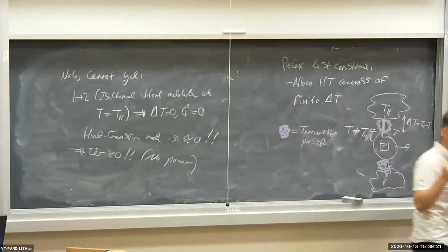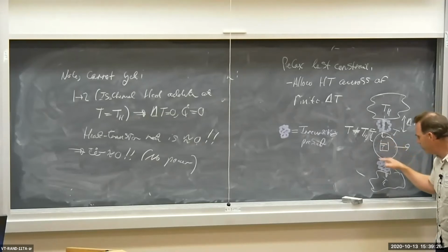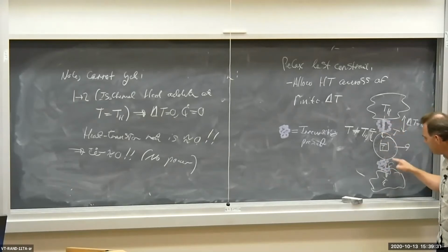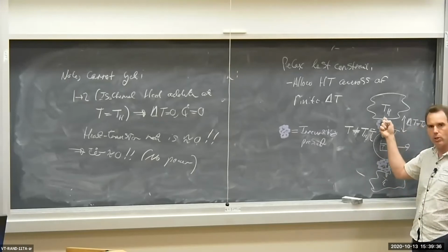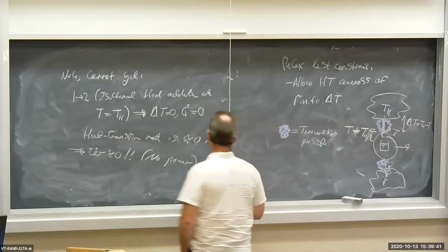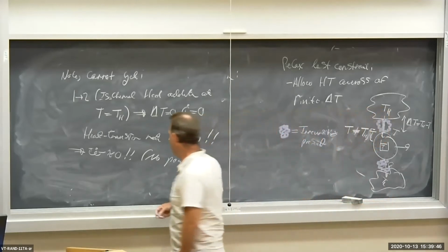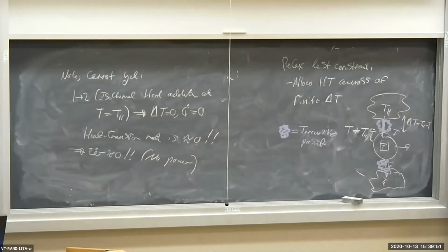In other words, the cycle that we're going to analyze is internally reversible. There's no irreversibilities going on inside, but there are external irreversibilities. There's irreversibilities occurring between the source of the heat, which is the high or the low temperature reservoir, and where it interacts with the system, which is at a temperature T. So we're going to allow for external irreversibility in our cycle, but not internal irreversibility within our cycle.